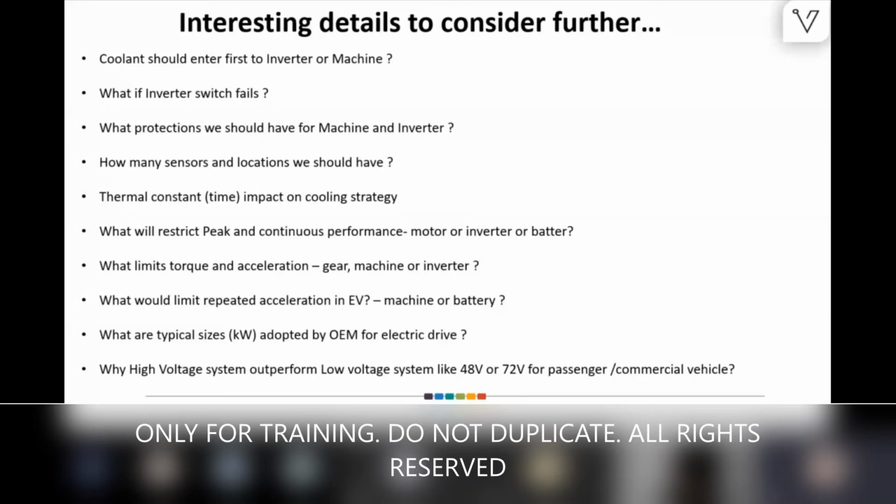So we have to see what kind of safety is needed, because each person has to do some certification before they touch above 60 volt. 60 volt is something okay to handle. Above 60 volt DC, it becomes a hazard, and we may have to go for some regulations or certifications. Those are all high voltage challenges, as we call them. We have to understand how to handle those safely.